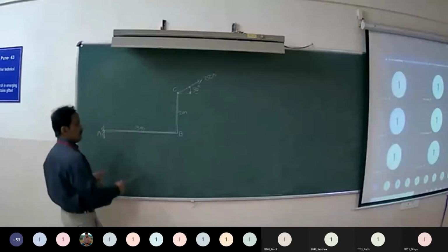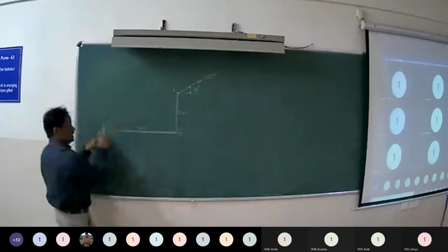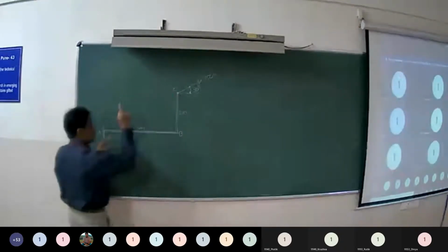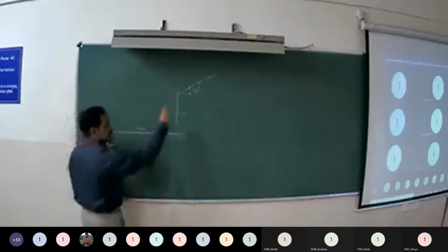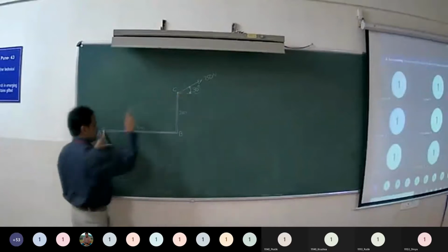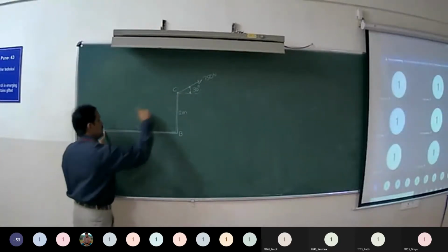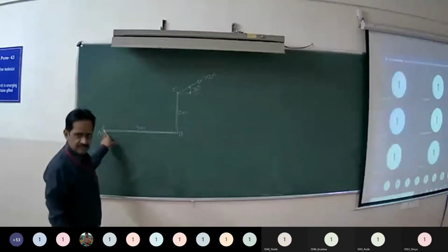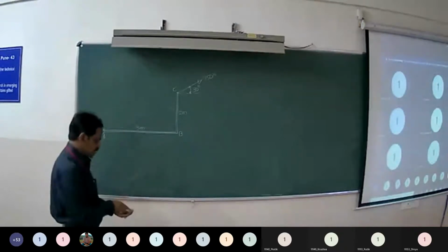Means to replace the force acting at C with force couple system at A, simply you find out the moment of 750 Newton about point A and then show 750 Newton at 30 degrees along with the moment. That is equivalent force couple system. Are you getting my point?